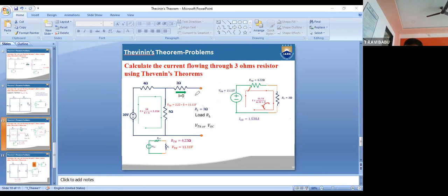When the circuit is closed, only then does current flow. So it is open now, so the current here is 0. So I am going to neglect this one. I want the VOC here. In this parallel circuit the voltage will be the same. This resistor is offset because there is no current. So the VOC here is the same, that is nothing but VTH.